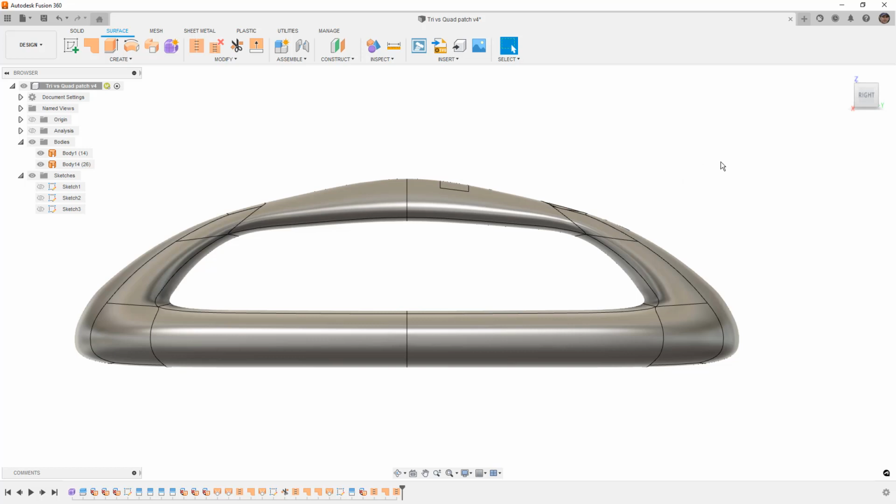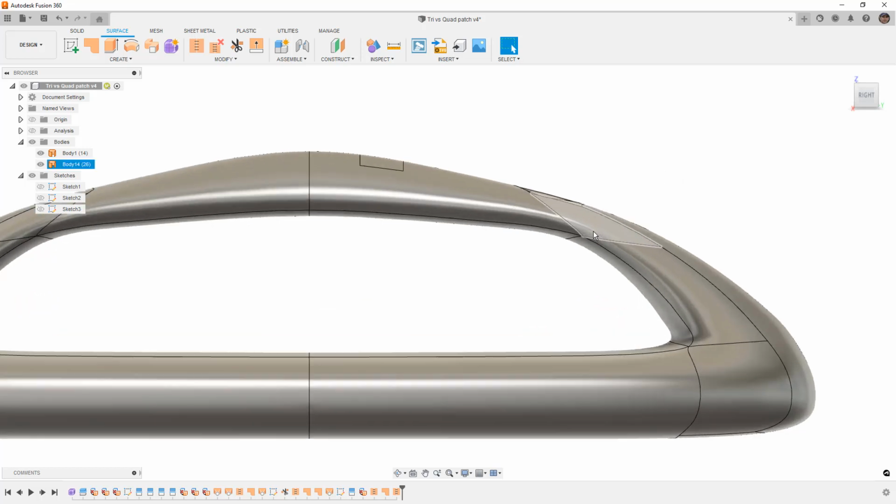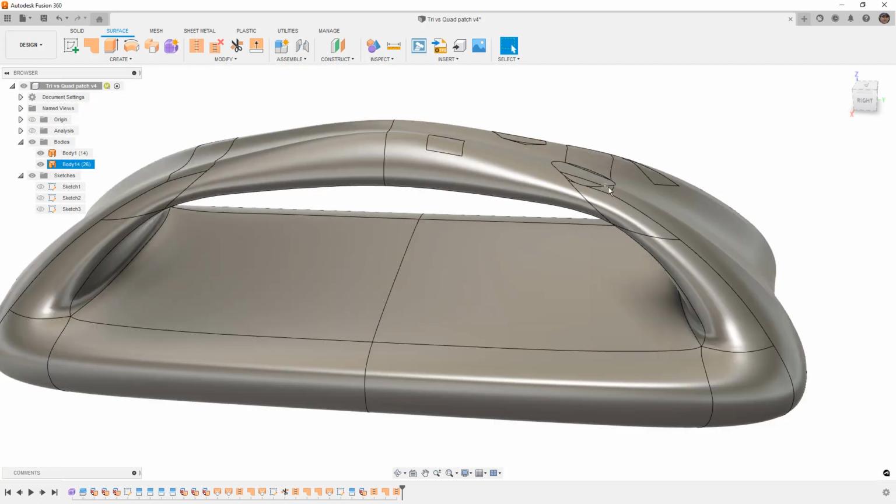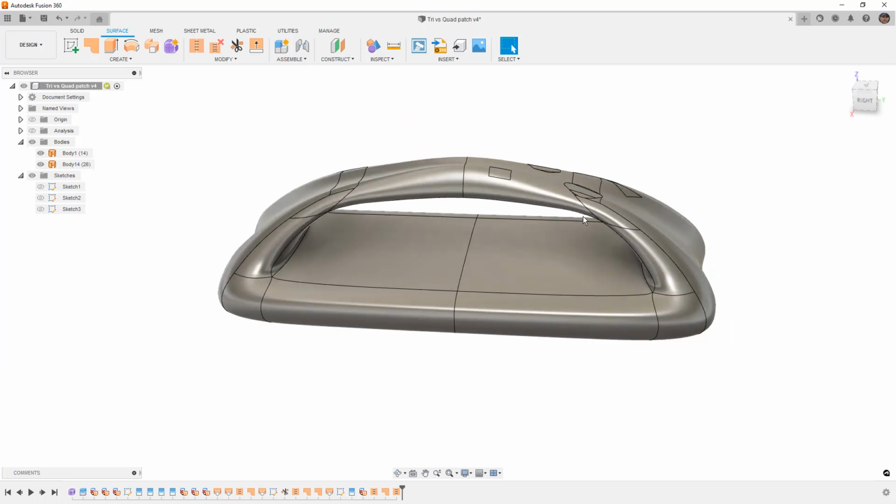It just doesn't work the same, which means that if you're trying to build this whole handle section again, you are likely going to do it by creating some cross sections in what you do have, and then deleting all those surfaces and then lofting between those cross sections. That's likely going to be your best case scenario. You also could use that opportunity to change the shape as you go through. But I think that's as far as I want to take this topic.